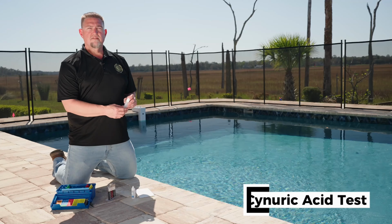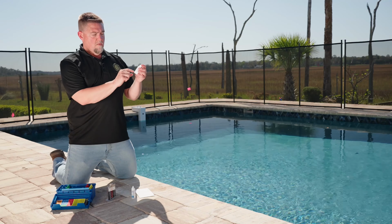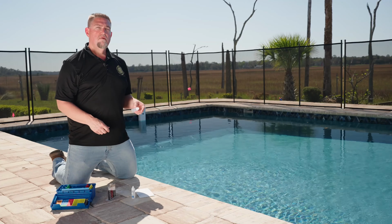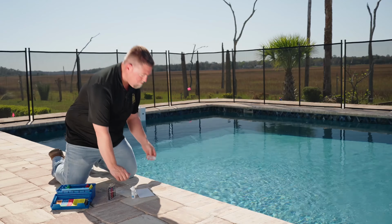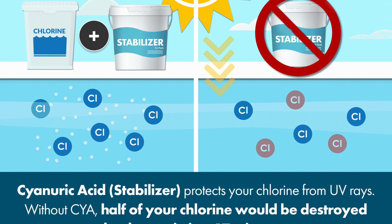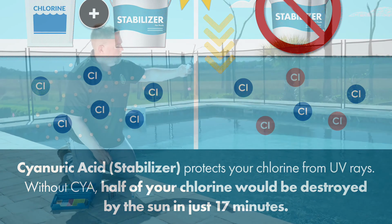Testing your cyanuric acid. Again, we want to take a different sample bottle this time. We're going to fill it to the 7 milliliter mark, in between the 2 return jets, elbow deep. So we're right at 7.